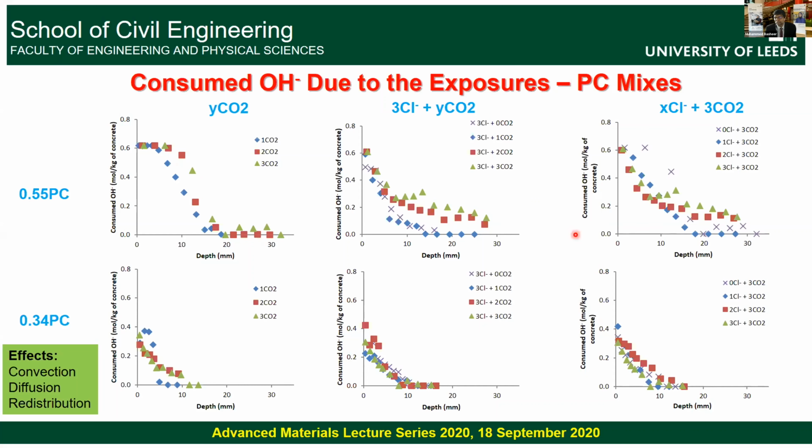And that depends on the amount of chloride present. And in here, with the good quality concrete, this effect we see here is not as dominant. So for this concrete, assuming that there is only one particular regime and a model should be sufficient, but for this concrete, that modeling is not sufficient.